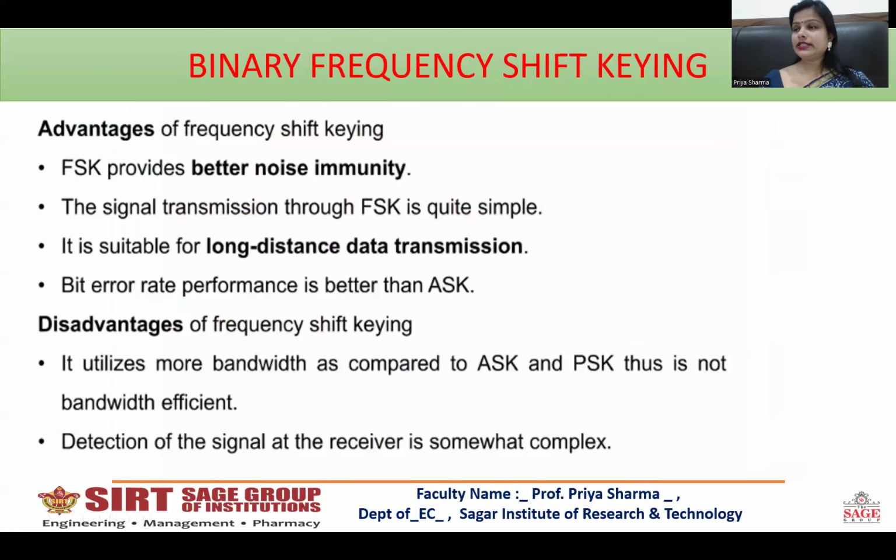Coming to the advantages and disadvantages of the BFSK. The advantages of FSK include that FSK provides better noise immunity. The signal transmission through FSK is quite simple. It is suitable for long distance data transmissions, and bit error rate performance is also better than amplitude shift keying. Disadvantages include that it utilizes more bandwidth as compared to the other shift keying procedures. Bandwidth is not efficient. Detection of a signal at the receiver is very complex.